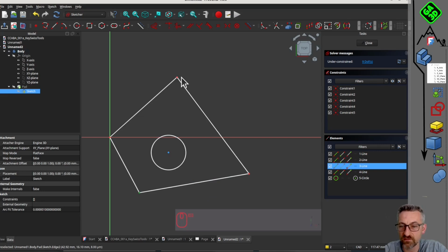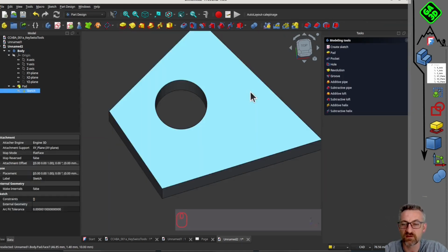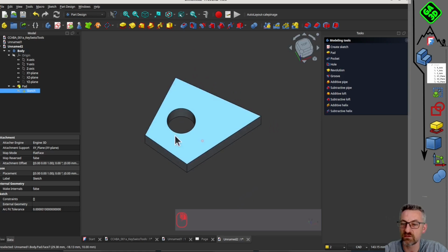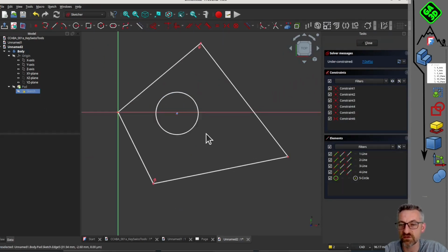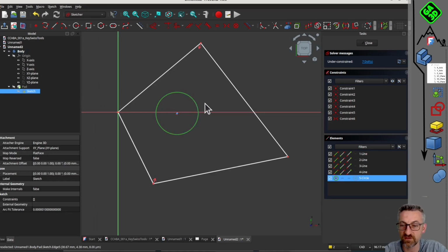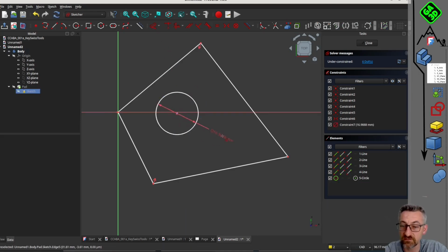And here are the constraints at the sketch level. For example, if we want this circle to be exactly at the top of these vertices, how do we do it? We click on this vertex, Ctrl on this vertex, and finally on the vertex we want these 2 vertices. And here you have a symmetry constraint. It automatically places it there.